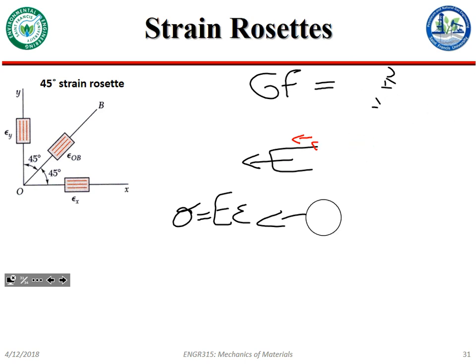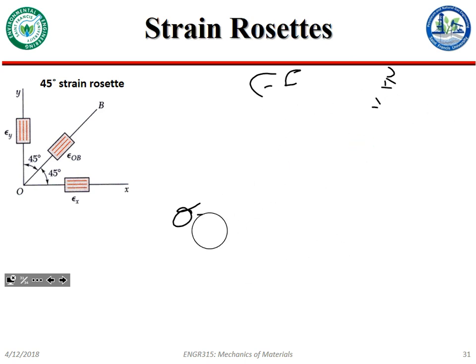All right, so how do we get there from here? There are a bunch of different ways that people throw down strain gauges. What I did here is have one in the lateral direction, the circumferential direction if you will, and then one in the longitudinal direction.